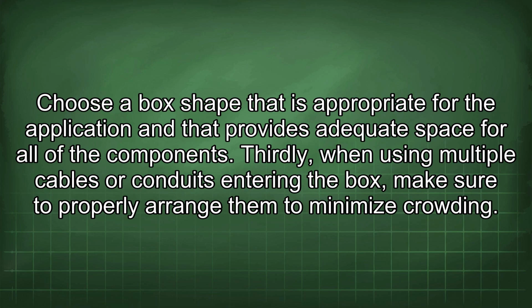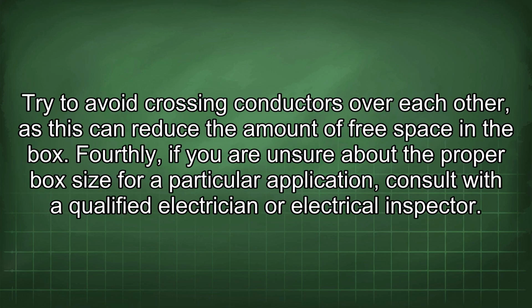Thirdly, when using multiple cables or conduits entering the box, make sure to properly arrange them to minimize crowding. Try to avoid crossing conductors over each other, as this can reduce the amount of free space in the box.